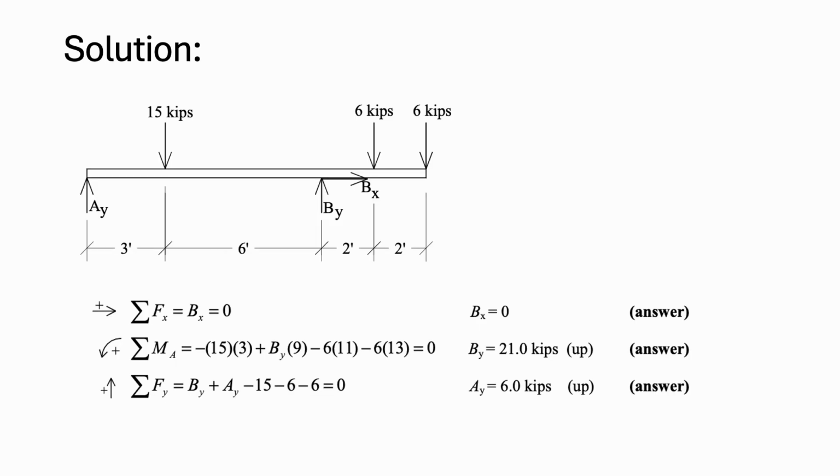So what we are doing, firstly, we need to draw a free body diagram. Since we have a roller at point A, we will have only one vertical force, Ay. Then we will have two unknowns at point B because it is a pin. And we have already mentioned the three point forces. So the next step is equations of equilibrium. The first one, sum of forces in x direction is equal to 0.